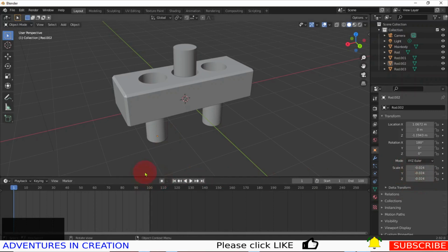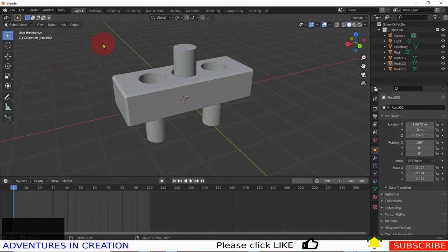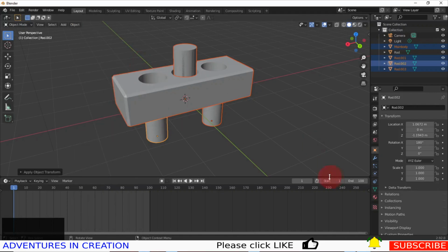So everything is scaled. I'm just going to go ahead and apply that by selecting the main body, holding down Shift, selecting my 3 rods, saying Object, Apply, Scale. So now you can see the scale goes back to 1.